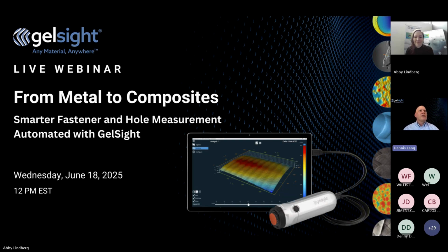We detect the gaps in the mating surface issues and protrusions that the typical tools will miss. And in addition to that, we output a 3D map where the fastener actually seats. So this is great. We can definitely start to help people predict load imbalance or fatigue based on the hole, whether it's new production or in a sustainment or MRO application.